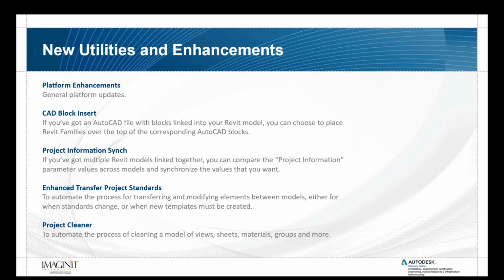is CAD block insert. If your designers are designing in AutoCAD, you can link that layout into Revit, and very quickly, with a few clicks, place Revit families where those AutoCAD blocks are located.